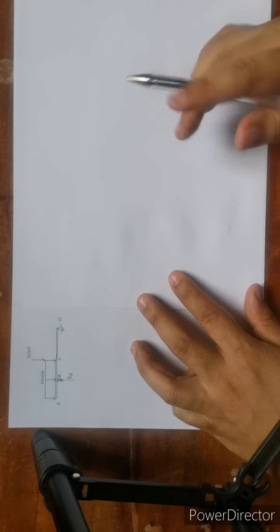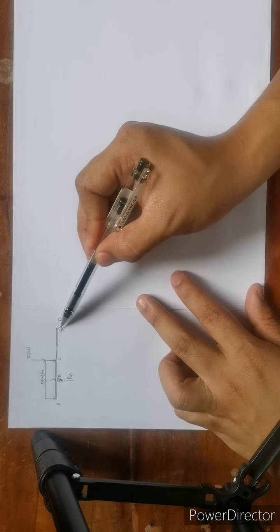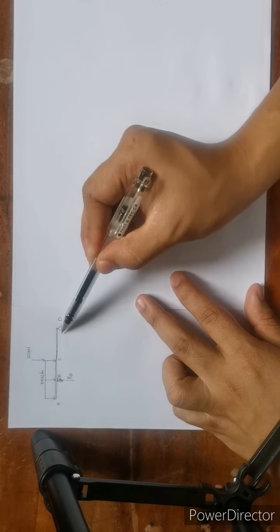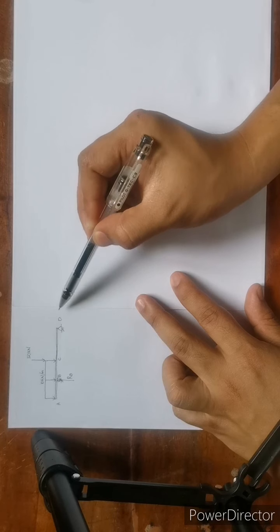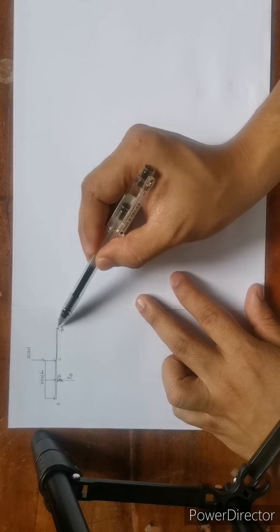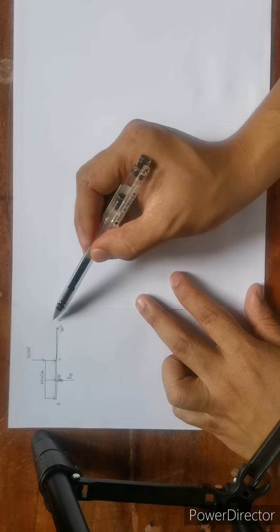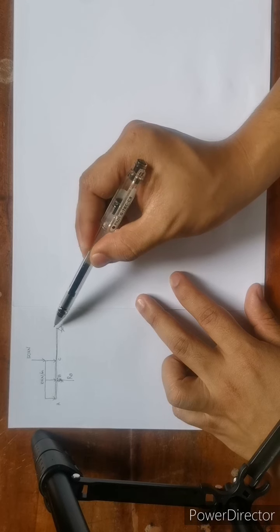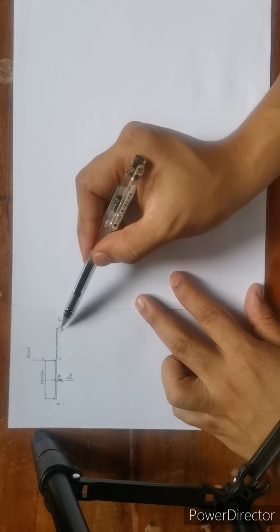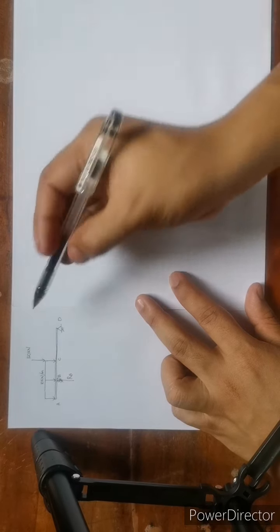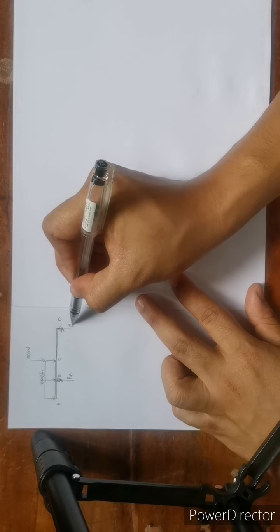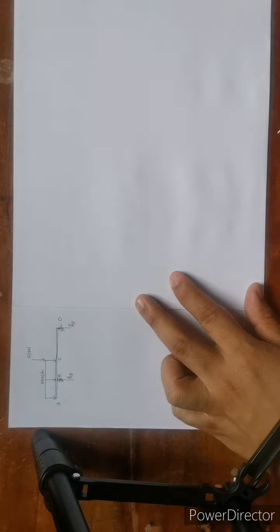And then, kay point D naman, meron tayong dalawang force na mag-act doon. And that is always perpendicular to the given surface and parallel to the given surface. Pero yung parallel force, parallel to the surface na force, is a horizontal force. At wala na ka-counteract sa kanya na horizontal force. Therefore, that is considered as 0. So, ibig sabihin, at support D, meron lang tayo ding isang reaction doon. That is vertical reaction at point D.